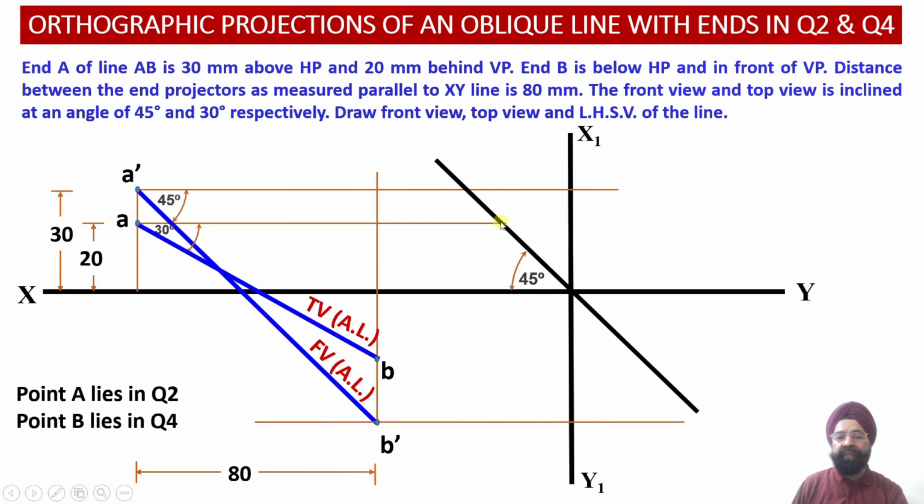Then here we have been able to obtain a point onto the transfer line corresponding to the plan projection of the point A. So point A has been extended in such a way that it provides us with the location of another point onto the transfer line. And the moment we reach this transfer line, from this point we are going to draw a vertical projector in the upward direction.